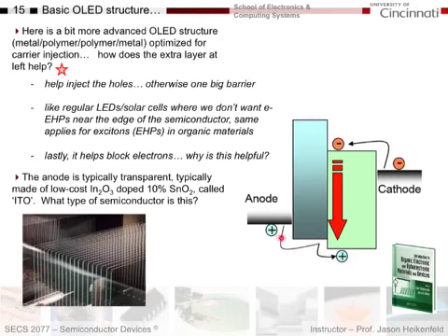This additional semiconductor, organic semiconductor layer was added for two reasons. One, it helps the hole injection. Instead of having to jump all the way this energy from here onto top of here, I can step it twice, which is much more probable than trying to go the whole distance. So it'd be like me asking you to jump from the floor onto the top of a chair versus 2 chairs high. Your probability to get to 2 chairs high would be much lower, much more difficult, right? So make it a step to make it easier.